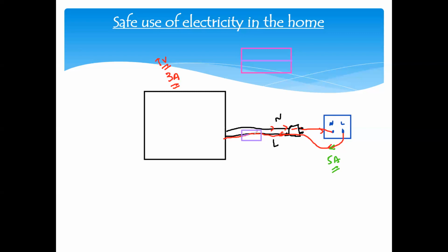And a fuse has its rating. Every fuse has its rating. Like if a device or a television needs 3 ampere, we can connect a fuse of around 3.5 ampere, a bit more than that. Not the same, a bit more than that, because it can survive a smaller change, but not a big one, like maybe 15 ampere coming, which will damage it. So every fuse has its own rating.